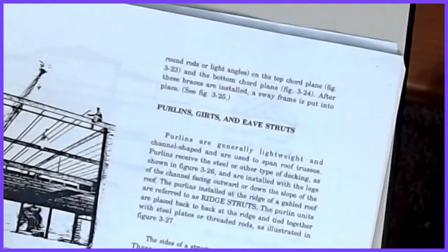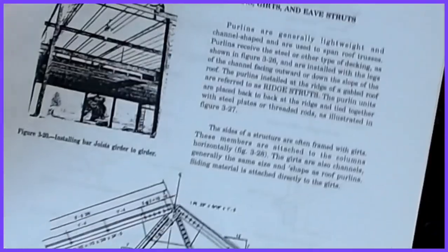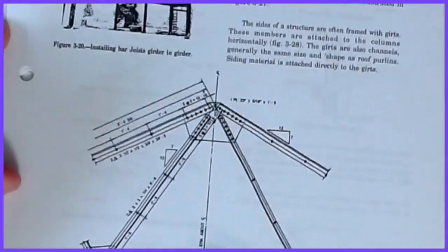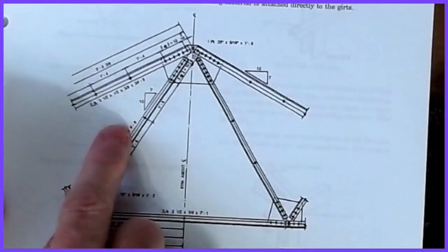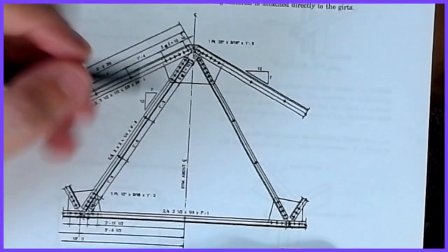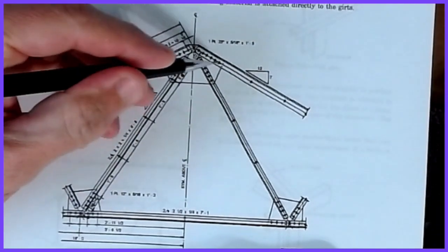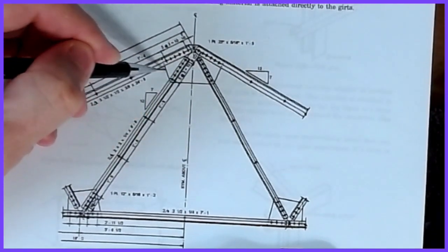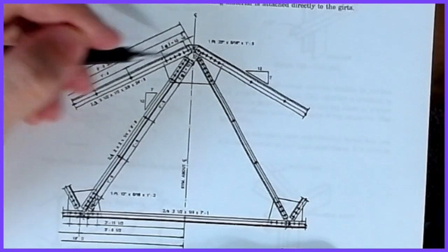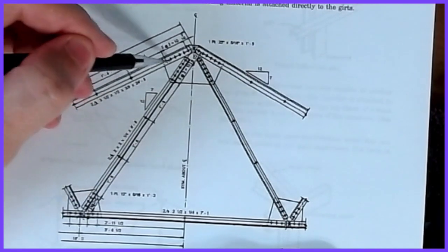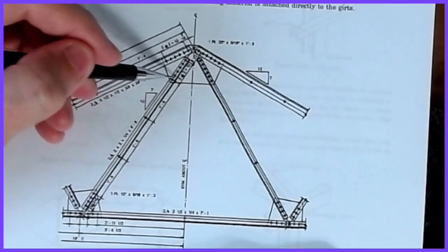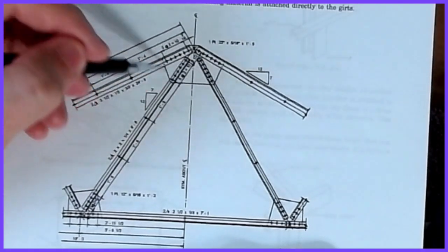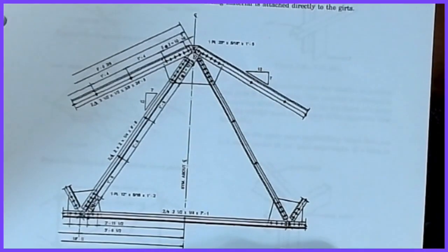So then we get into talking about purlins and girts and trusses. This is kind of the connection of, if you weren't doing a truss like the open web steel joist, you can build your own. And so you'll hear the term gusset plate tossed out, and that's what this piece is. You can see that I have an angle that's come up. We've drilled a bunch of holes, and this plate bolts to those angles, and this member lines up with another set of holes on the same plate. And so there's some design that goes into work on these gusset plates as well.